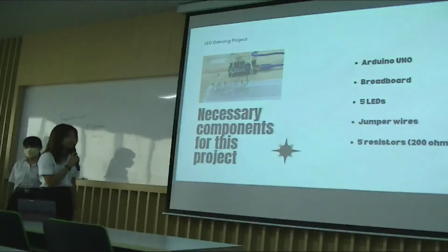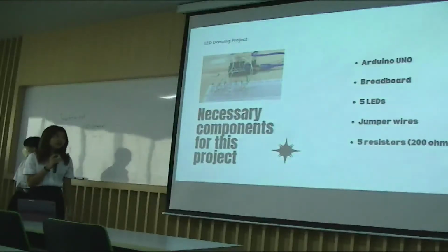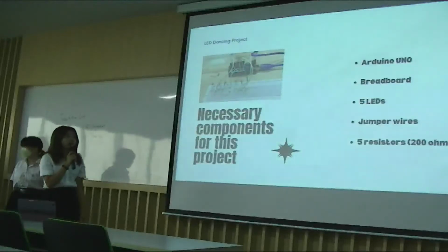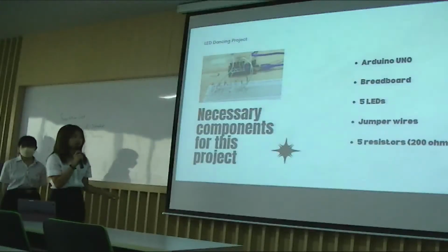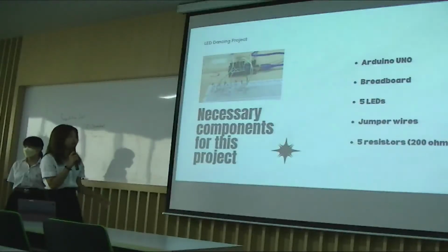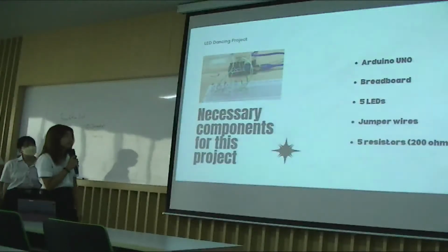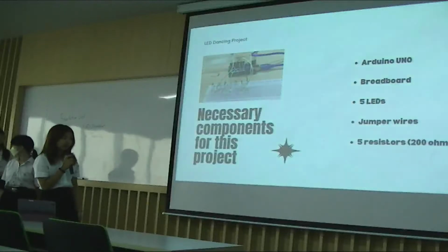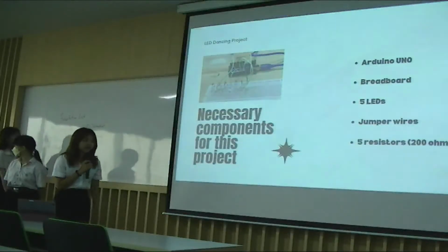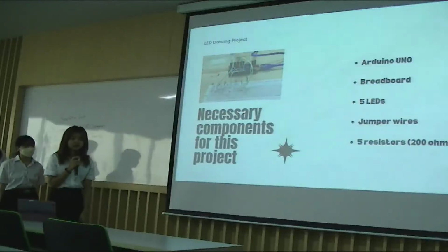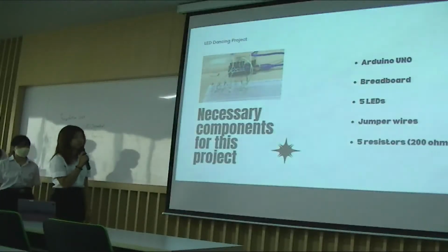Okay, so in this project we use Arduino. It's really useful and easy to use for students, and we also use a breadboard, 5 LEDs, 6 jumper wires and 5 resistors. Here we use 200 ohm resistors so that the LEDs can produce light.